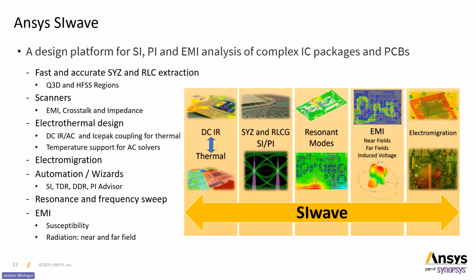And here we're considering the layout of your PCB. We're considering the ohmic losses that you have due to currents, right? You can extract S-parameters just like a full wave solver. You can run signal integrity analysis and generate those eye diagrams. You can compute resonant modes, which is extremely important for EMI.